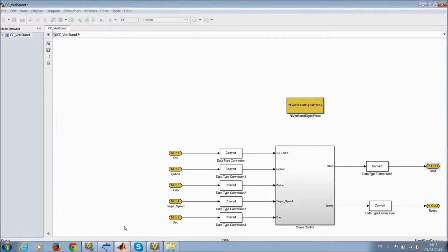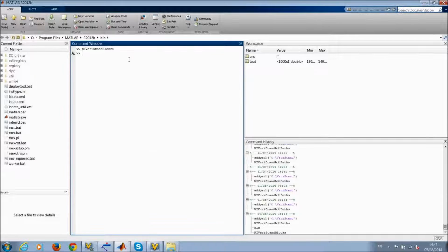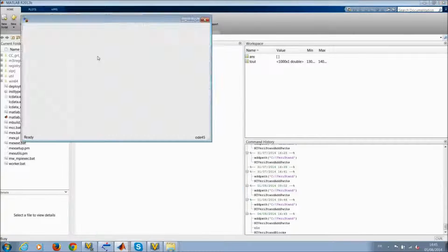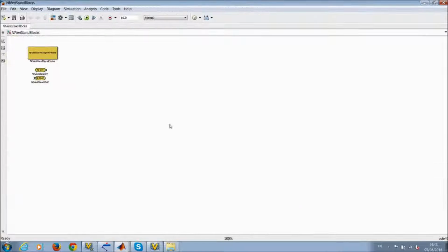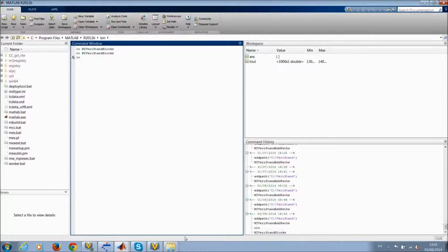You also have to specify the input and output variable types accordingly with the signals used in the Simulink model. For this, I advise you to use conversion blocks between inputs, outputs and the model to test, for a data type system simpler and faster. For this demonstration, all the inputs and outputs are doubles.